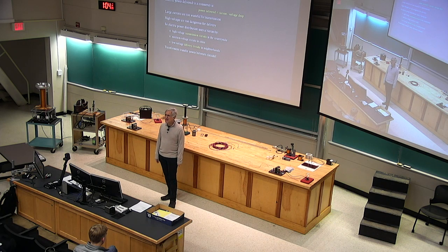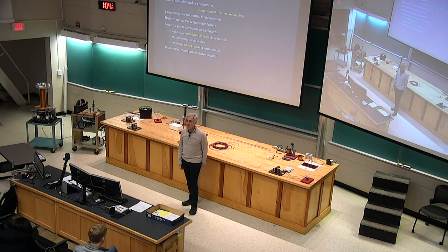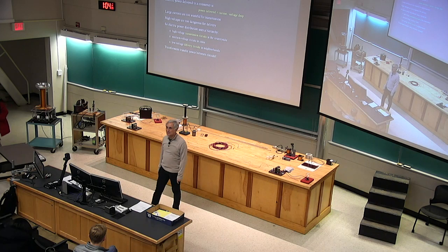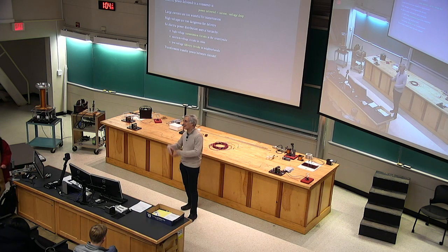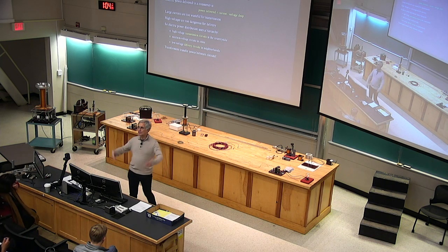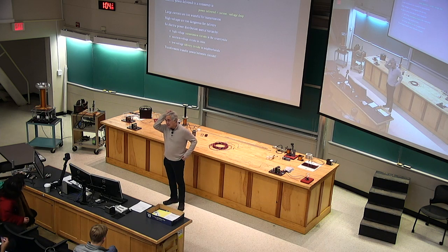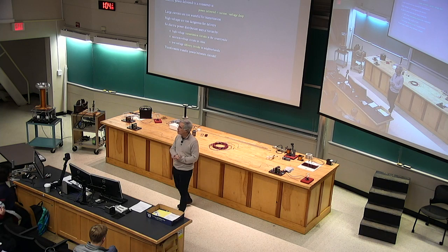Something like 6% of the generating capacity of the US is consumed in the wires delivering the power. So it's a non-trivial amount already, and if you just doubled all the current in all the power lines, you would quadruple the power waste. You'd go from 6% to more like 18%. You probably have to divide by 2 because you've doubled the power. But anyway, it gets to be a large fraction of the power generating capacity of the country. So not a good idea.